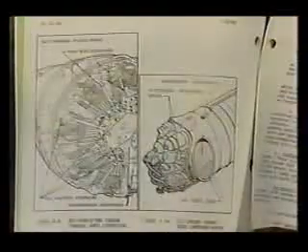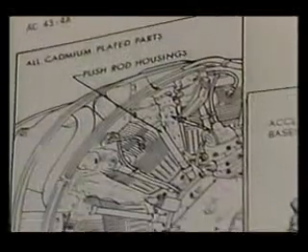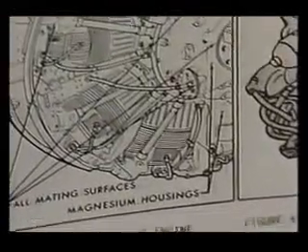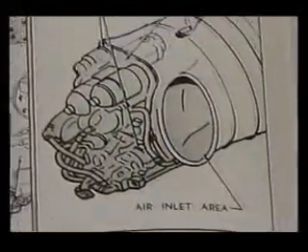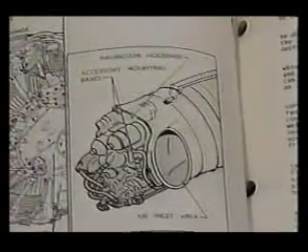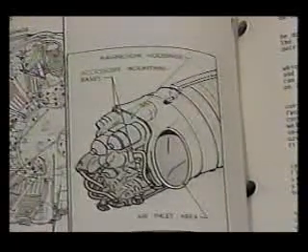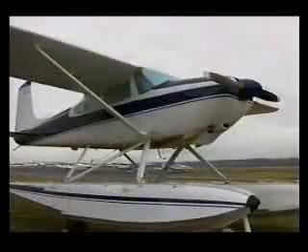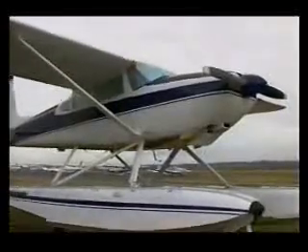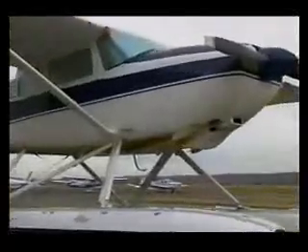Engine frontal areas and cooling air vents are routinely exposed to airborne dirt and dust, runway gravel, and rain. Engine accessory mounting bases may have small areas of unpainted aluminum or magnesium on the machined mounting surfaces. This makes them prime targets for corrosion. Inspect all sections of the cooling air path completely. Pay special attention to obstructions and crevices where salt deposits may build up during marine operations.